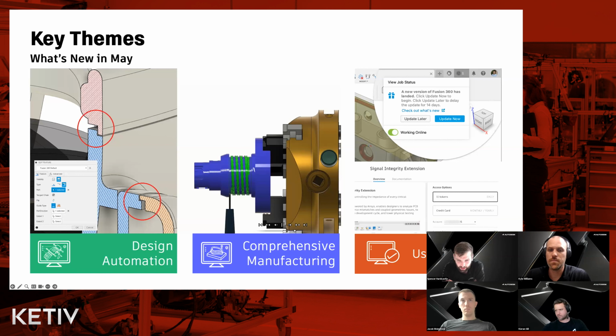It was a really common request for those that did use parameters to start using expressions, to start using logical operators within that dialogue, to start building a lot more complex scenarios and situations where you change one parameter, and not just the size and shape of the part could change, but the fundamental design principles behind that design could also change. And that's what adding these conditional expressions brings. And so a whole series of automation enhancements there. And like I said, keep your eye out for different pieces of automation all the way through each and every workspace.